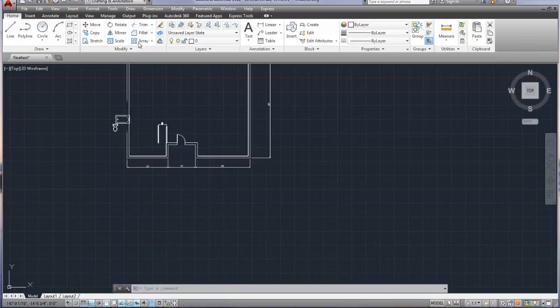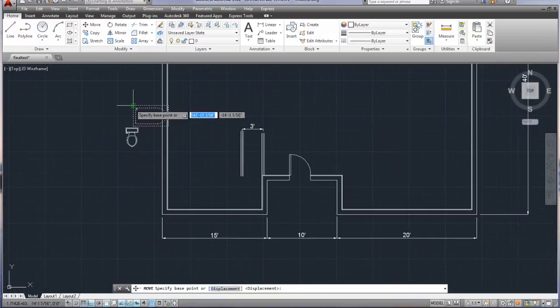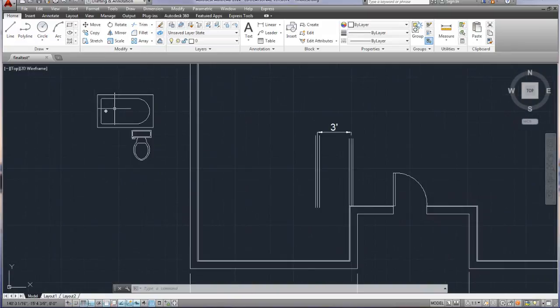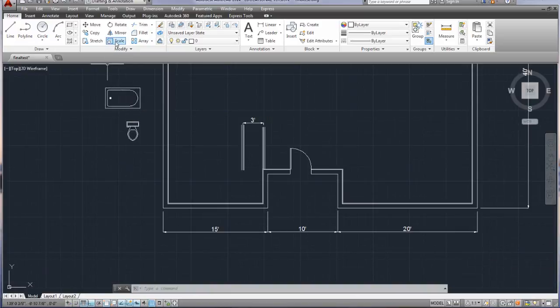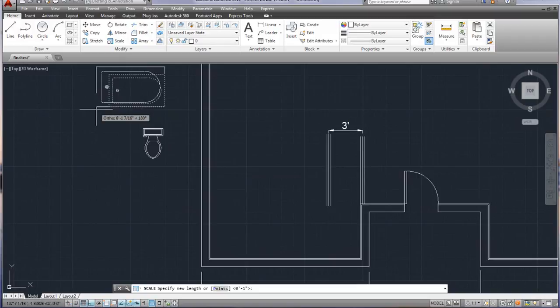Now if I need to go through, and once I go through and rescale those, I can do that. I can either explode them, so I can explode an object, alter it that way, or I can go back and just scale it, whatever scale I need. I can type in scale, click R for reference, click here, which is the original object size, and just make it whatever size I want to. So I can make it 5 foot to 6 foot, and there you go.